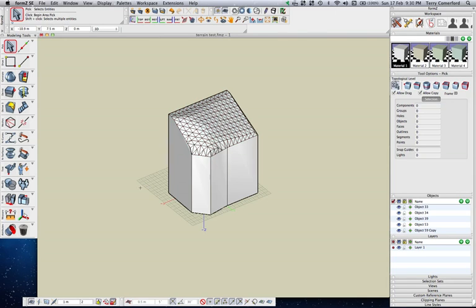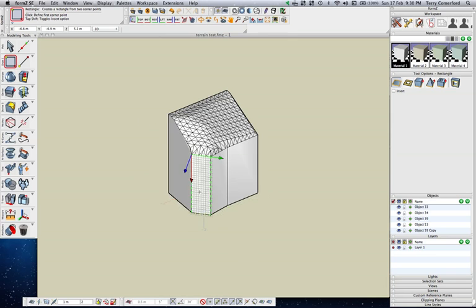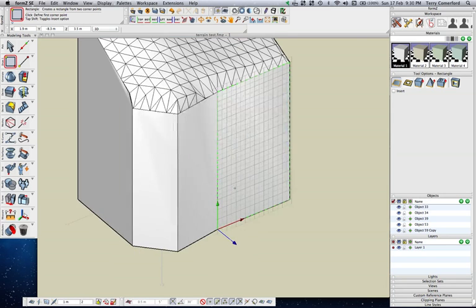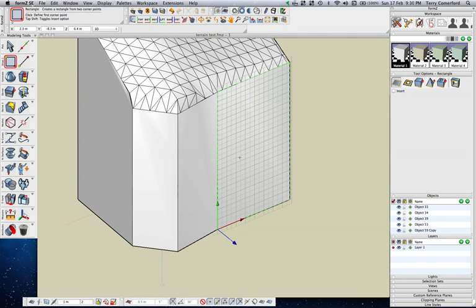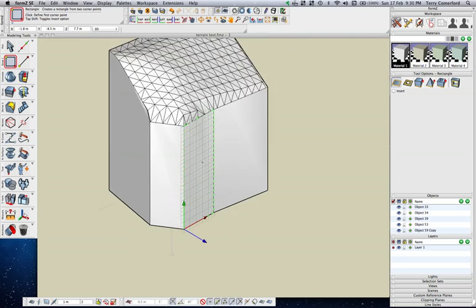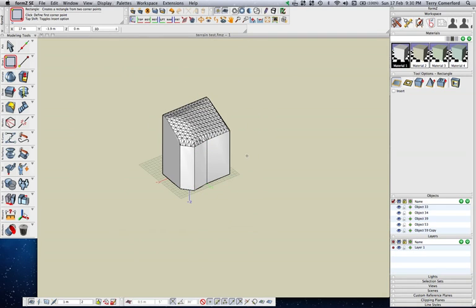The reference plane is a bit of an issue. Just have a look and see if I start drawing any sort of geometry. As I hover over the model, you can see how it automatically snaps to the reference plane of the face that I'm hovering over. Now sometimes you don't want that to change, and this is an example where you don't want it to change.